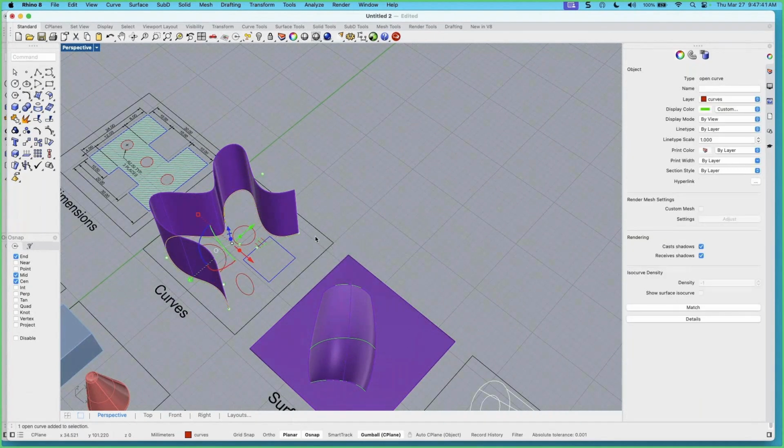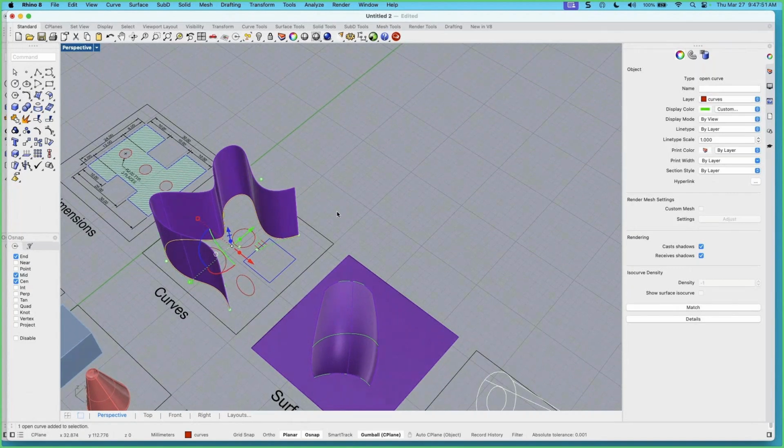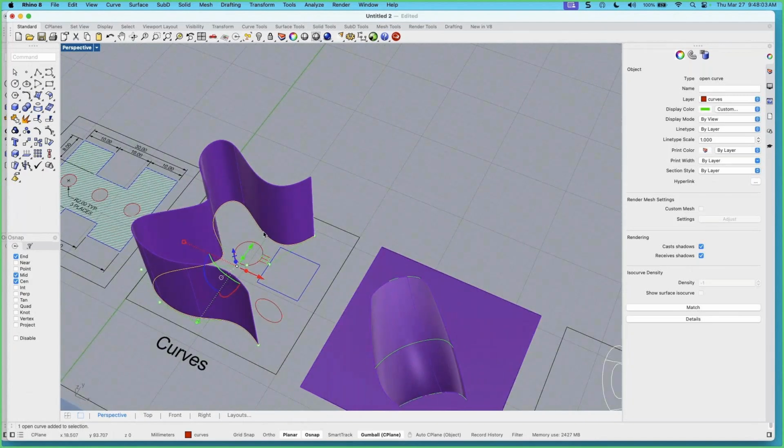It was added in Rhino 5 and fundamentally changed the way we edit in Rhino. Now, not without keeping the technical options, but they're still there. Move, copy, scale, rotate, those are still there. But I can do those functions with the gumball very easily on any geometry.